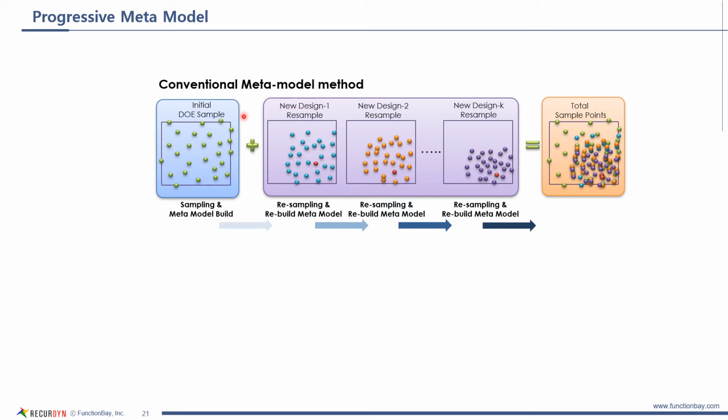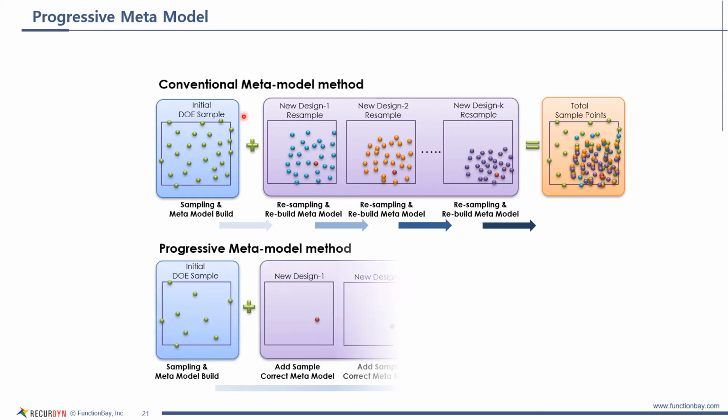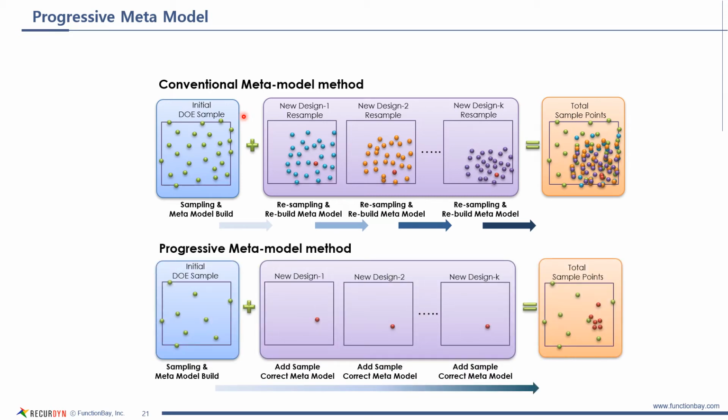Progressive MetaModel has a unique algorithm that can reuse the previous MetaModel. Therefore, it only uses one sample. So, after the solver finds the optimal result may exist on the right side, only one new sample of data is needed, which means there is only one simulation to run.